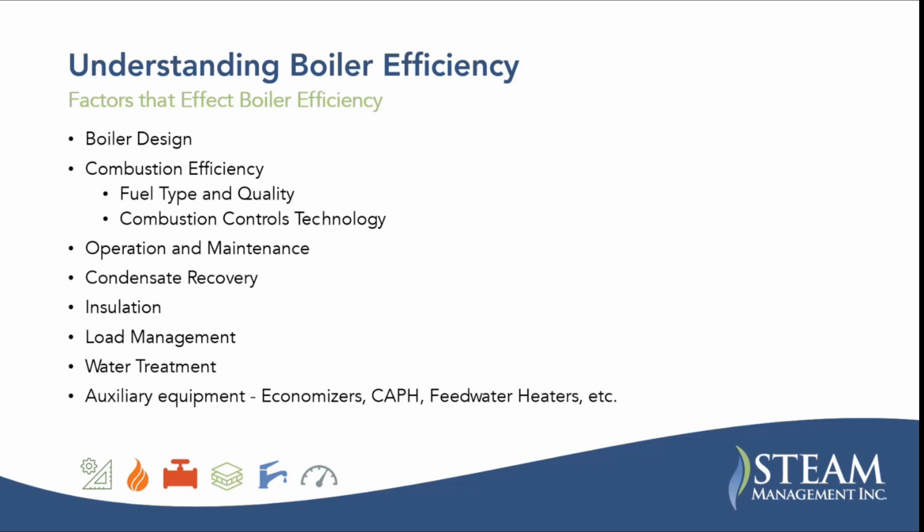Operation and maintenance. Regular maintenance and proper operation are essential for keeping the boiler running efficiently. Condensate recovery. So obviously, from a system standpoint, returning condensate is conserving energy, but from just the boiler envelope itself, you're talking about getting more clean water into the boiler, which is resulting in less scale on the water side of the boiler and less blowdown required. So improving your condensate recovery obviously improves your system efficiency, but it does improve your boiler efficiency itself.